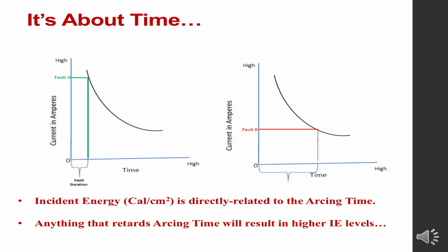So from an arc flash hazard standpoint, what I want you to realize is those fuses are in the high voltage winding, which means the fault current is much lower than on the low voltage side. So the fusing isn't going to respond very quickly, and you're going to be working on the side of that transformer that has a lot of current flow, a lot of short circuit current, which means arc flash hazards for you. So here's my final point before I hand you off to Bhanu.